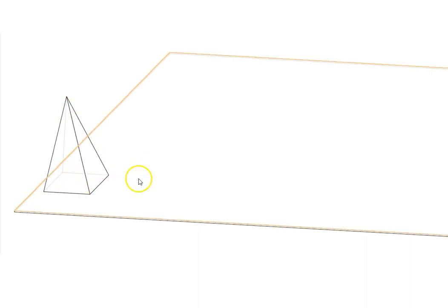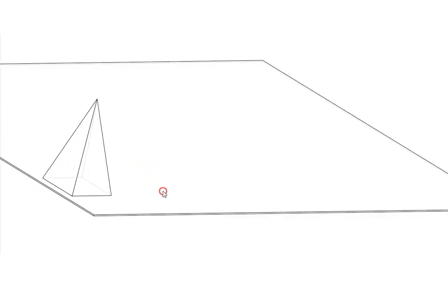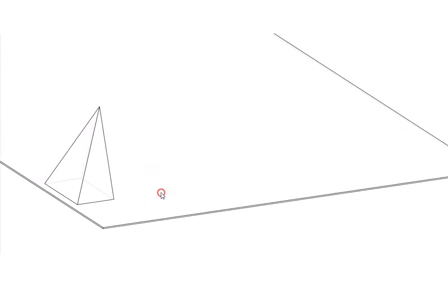As a quick tip, while drawing projections, one of the most important things you'll have to look at is the boundary of your projection. When you look at a solid, the boundary edges will always be seen. The boundary edges are something which you can draw using continuous lines, and the lines inside are going to be hidden. This could be seen even as you rotate the solid and look at different orientations.